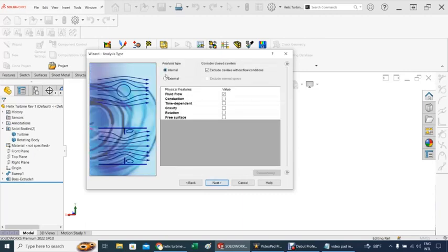Next, it's gonna be external, not a big deal here. Now fluid flow and rotation, excellent. We're gonna be using the local region averaging. Well, that's what SolidWorks said, particularly because you have a kind of constant distance between the turbine and the outside of the turbine, or the rotating body. Since everything is constant, this is the best way to do it. I'm only clicking here to show the other stuff. There's local region and global rotating. Gonna be using local region.